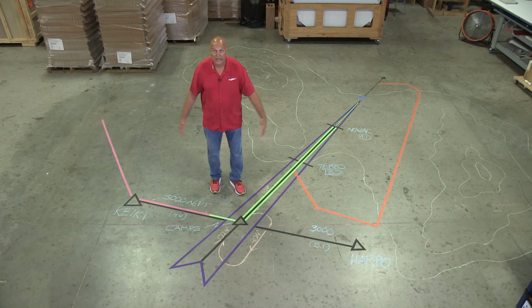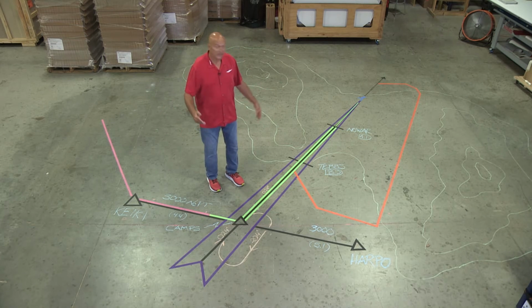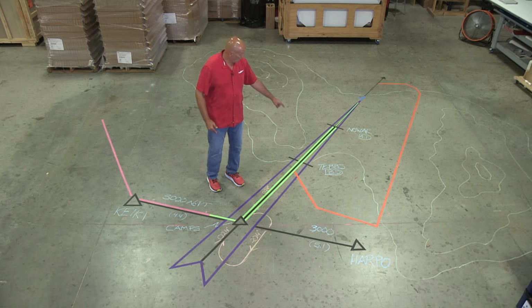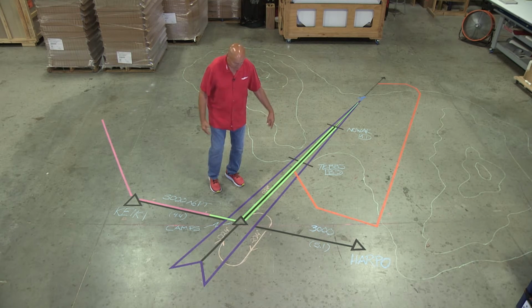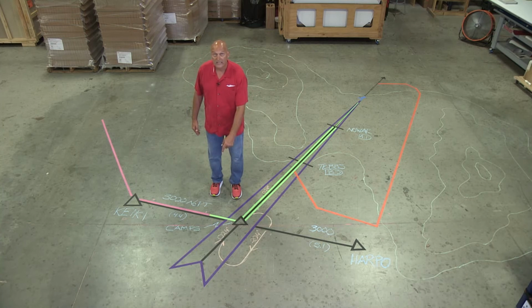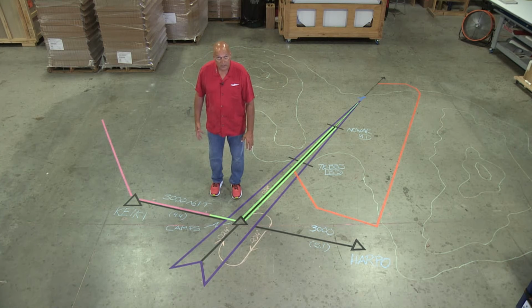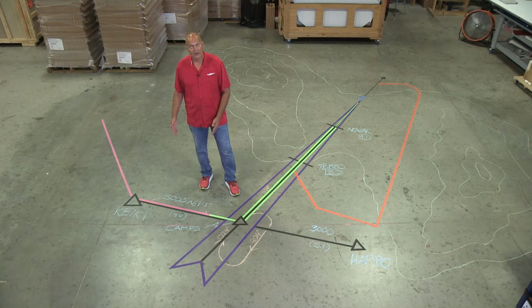When you're looking at the approach, understanding where your fixes are, also being able to label the DME on your approaches. Again, do you have any holds here? Do you have any procedure turns perhaps? Are there going to be procedure turns? Where aren't there going to be procedure turns? And make sure they label them out.